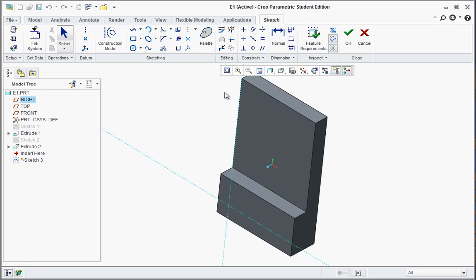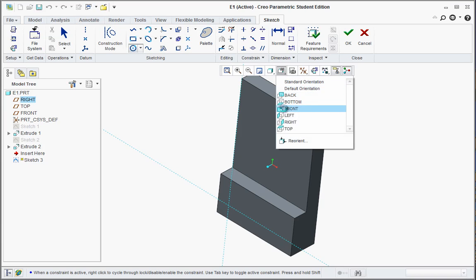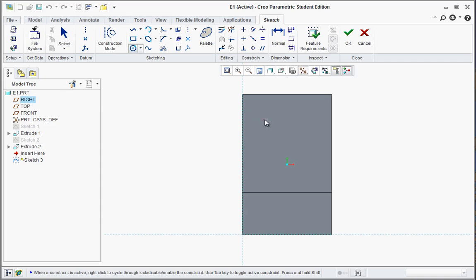So we're sketching on this surface, so you can now take the center point tool, which is a circle tool essentially, glide up to this upper left quadrant. Now if you prefer, again, you could go to the AB button and go to front. This might be helpful. And so the upper left quadrant, click and drag out a circle, and the middle click a couple times. And you'll get the dimensions to appear. Some of these we want, some of them we don't really want. According to the book, we actually want this one right here, and we're going to make that an offset of 1 inch from the left edge.